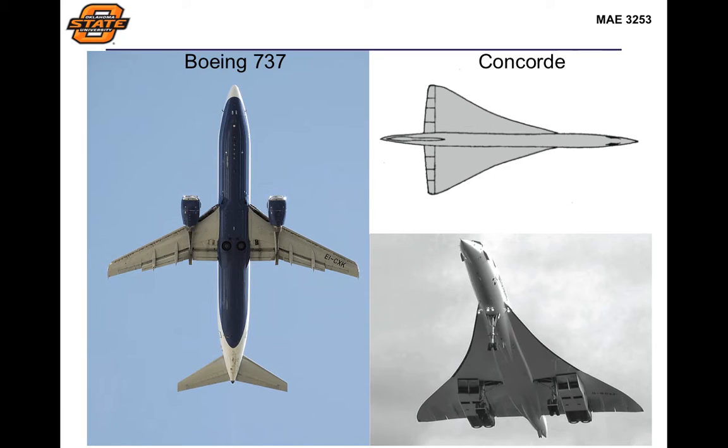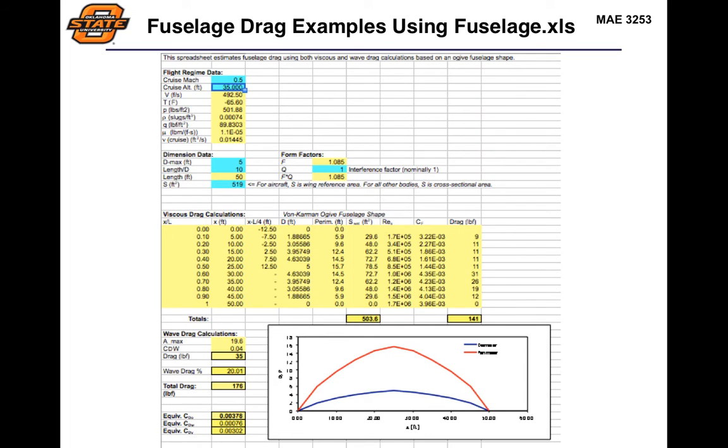You'll note if you look at something like the 737, you do have a lot of asymmetry between the nose cone section and the tail cone section. Trying to reduce that drag from the nose cone gives you a similar type of design between the nose cone and the tail cone. But keep in mind what you're trying to also do here is minimize your manufacturing costs as well as logistical considerations for the overall aircraft, how you're storing passengers on board and everything else.